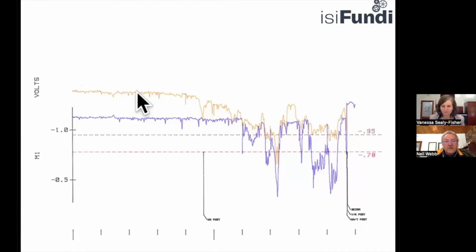So this was then subjected to effectively direct assessment. And it was found there was just the wrapping that had failed. And because the rectifier had been kept operational, there was no metal loss on the pipeline itself. It was found that section of pipe was in fact in good condition and was able to be used as found with just 1 kilometer of rewrapping instead of 10 to 15 kilometers of replacement. If you think about the scenario, it really was the perfect storm, and it's lovely that cathodic protection can avert these dreadful storms. It's really quite encouraging from a CP perspective.